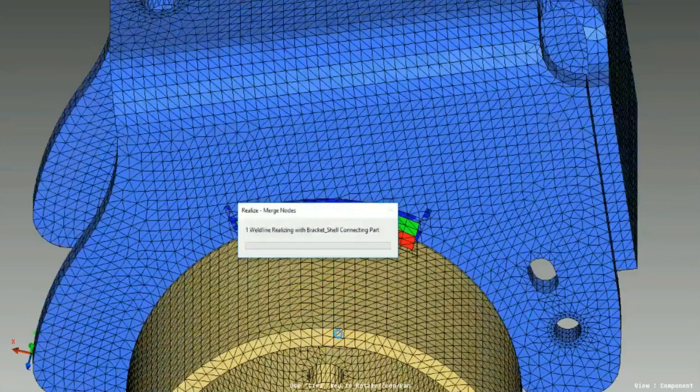Just to recap, we started with selecting the 1D elements on the model where we want to create the weld, and then we specified the master component and the slave component. Then in the solid weldment inputs panel, we specified a number of parameters such as the number of layers in the weld, the element size, the element width, and also the profile of the weld.